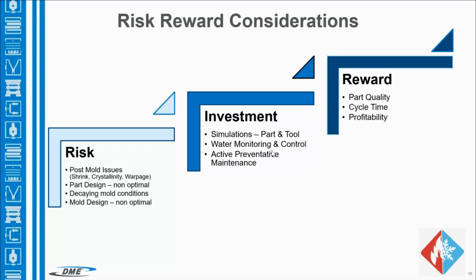And one thing we're going to keep saying is you have to invest in water monitoring and control. I don't know how many times I've walked into a plant and, we're making bad parts. Well, do you have water flow? And I watch somebody walk over to the machine and grab the hose and say, yeah, I feel the water flowing through the hose. Is it actually going to the circuit that you want it to? Does it have the right flow? Is the line partially plugged? You don't know anything, and you're flying blind. So you've got to invest in water monitoring.